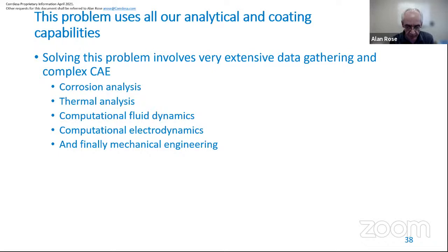With some processes, you might have some off-gases and some smells or whatever. With the Dualistic, we did some measurements where we had monitors on the shoulders of the operators, and because the air was being sucked locally at the point of application of the repair, there was less contamination in the air, so we didn't need additional local ventilation. So basically, gloves and glasses.